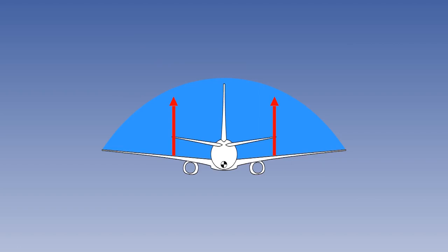The illustration shows the low pressure area on the top of the wing. Each half of the wing generates a share of the lift, and each component of lift will act at a certain distance from the CG. Any change in lift in a side slip will act through a given arm length to generate a rolling moment.